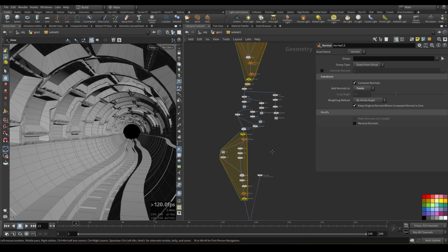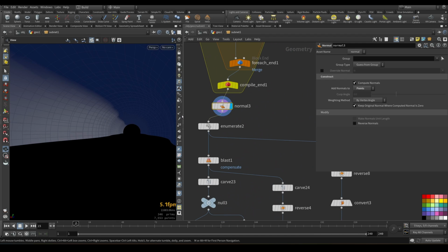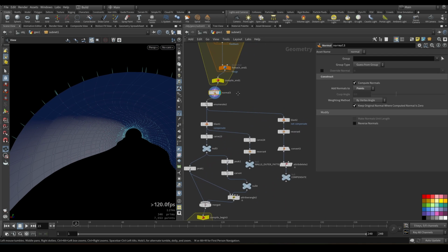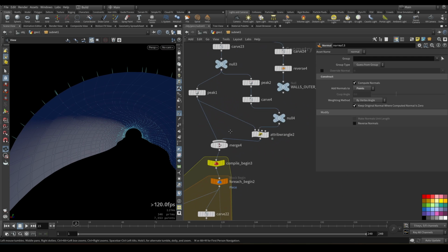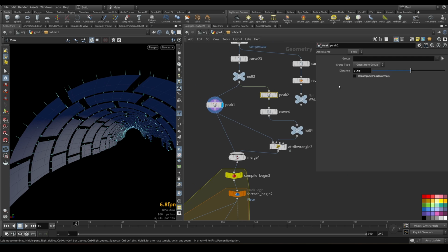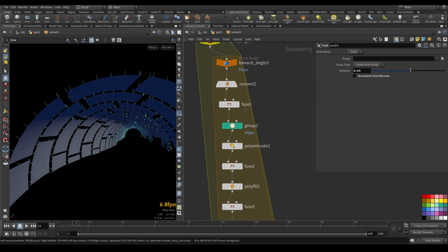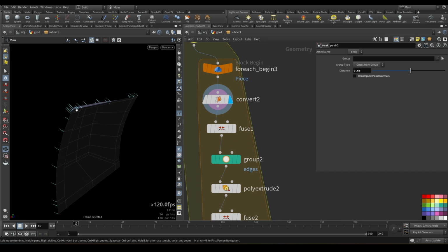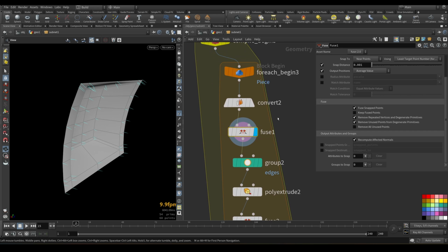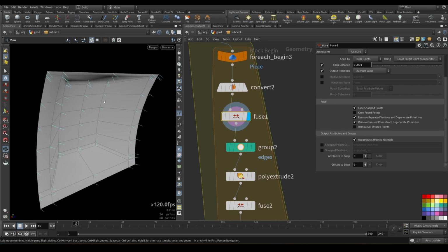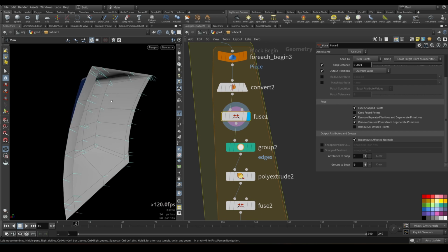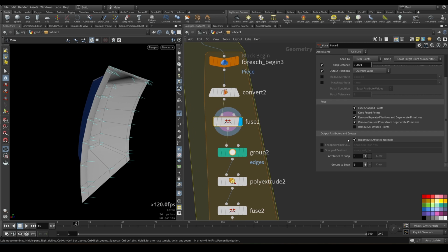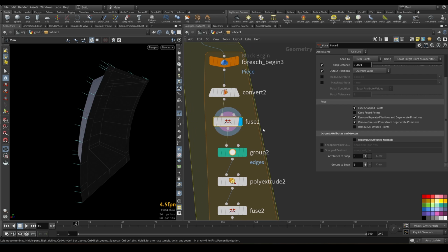It's not obvious, but we have unpredictable normals. Here, as you remember, I've created normals and wanted to carry them over my graph. I've defeated pick node. I disabled recompute point normals on that. But here, when I apply fuse, as you can see, for example, I have predictable normals that I've set. After fuse is applied, you see my normals are pretty much all screwed up. And it's pure luck that we have a predictable result. So we should disable recompute affected normals on fuse.